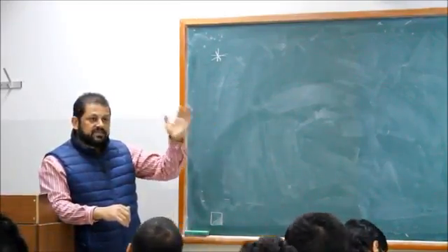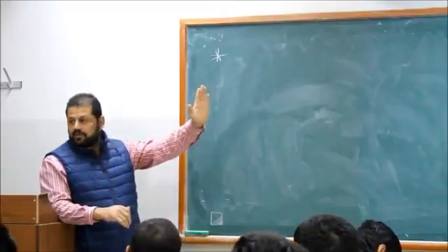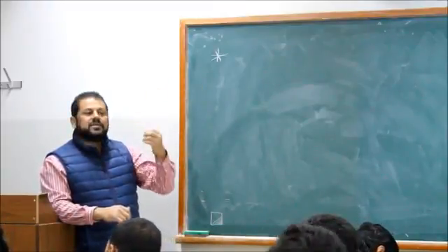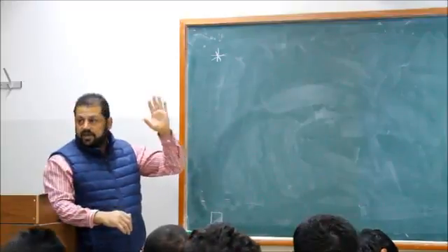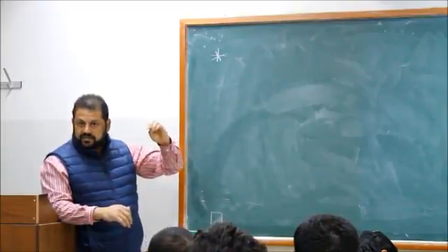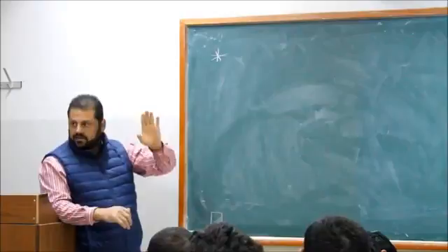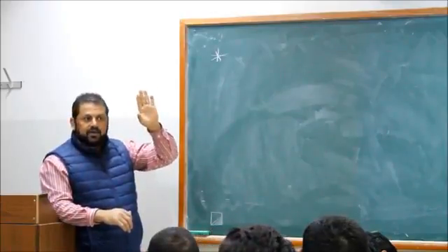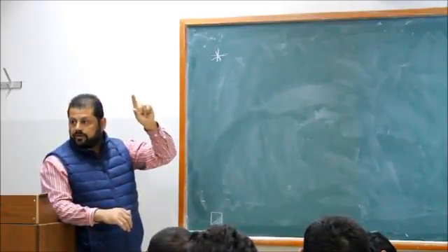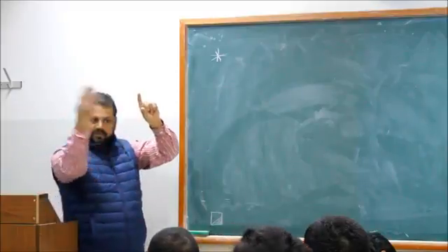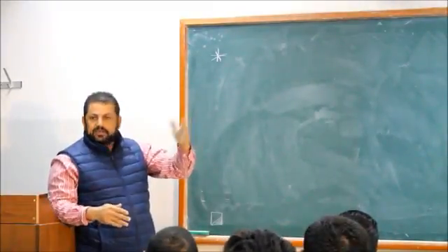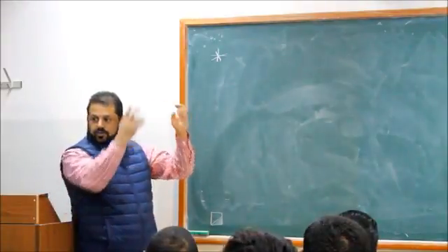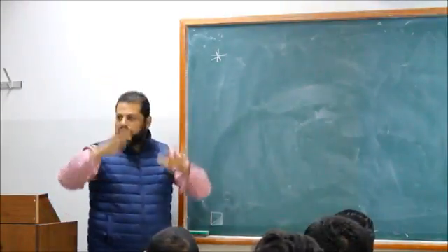How we solve frames that have side sway. When side sway is allowed, in beams, if we have side sway, one support will settle. That settlement should be known. From that settlement, from the tables on the right and the back of the cover of the book, we can calculate fixed end moments. Then we put them in the right location and you put in the solution.